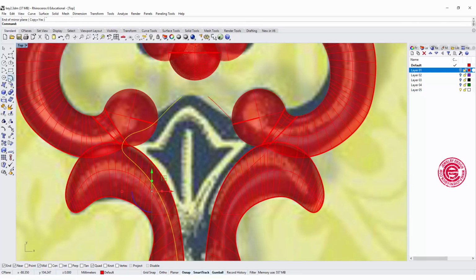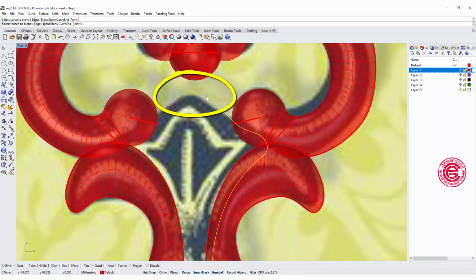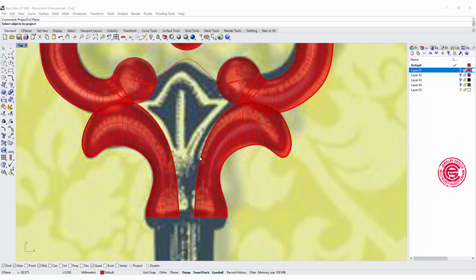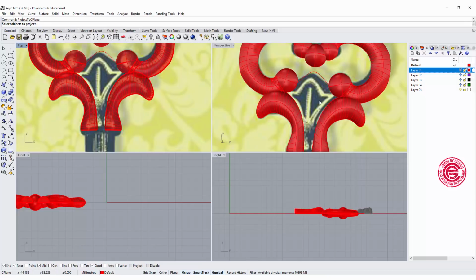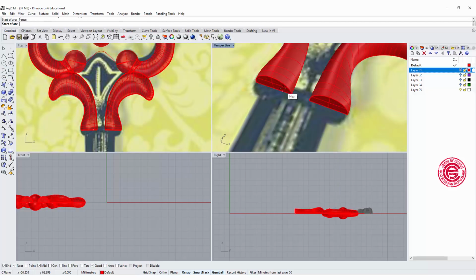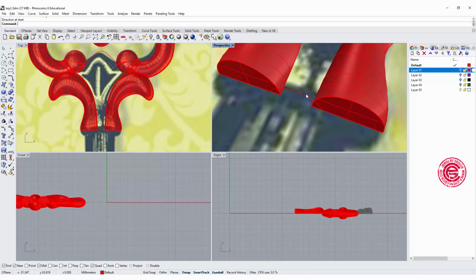Okay, and try to blend again. I use a lot of blend in this tutorial. I just want to show you a different way of how I work with curves. And we want to go to the perspective view, and let's use the same commands for the arc, snapping into the endpoint, holding the shift at the right view, and create this arc.